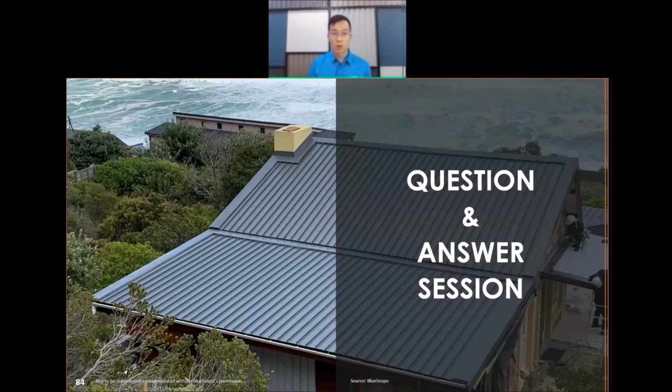So it depends on what kind of metric you use. Typically there's a standard where we measure certain chemicals in the air, or what we call precipitation in the air, that is considered a marine environment zone. The standard, if I'm not wrong, is called ISO 9223. But of course, for us from BlueScope, in the Malaysian context, 1 km from the sea will be considered within marine influence. Of course, a different location or country might consider it differently.